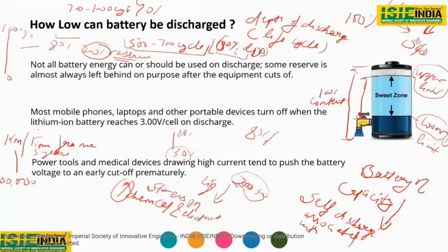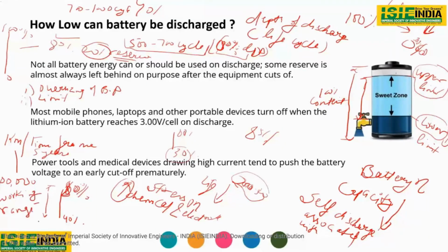But how they are able to provide this warranty is, first of all, the oversizing of the battery pack, and there is a limit of charging and discharging. As I said earlier, in electric vehicles they generally follow this rule: 40 to 80% or 75%. So generally you operate in this range. This is your working range, and you operate within this range only.